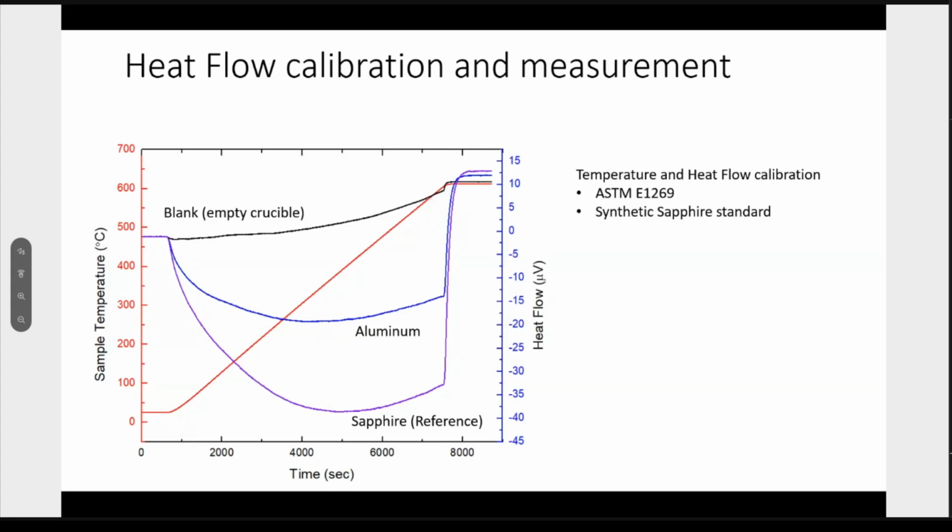For the calibration, we follow the ASTM standard. By comparing the experimental heat flow and the synthetic sapphire data tables in the NIST standard, we can obtain the value of sensitivities for each point of measurement.